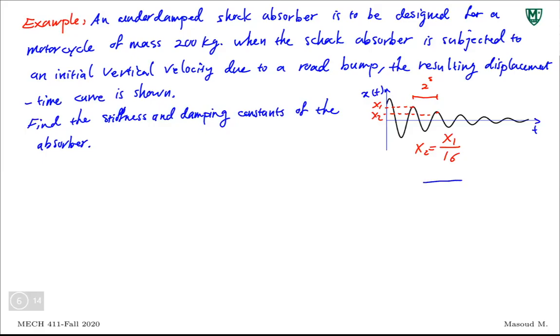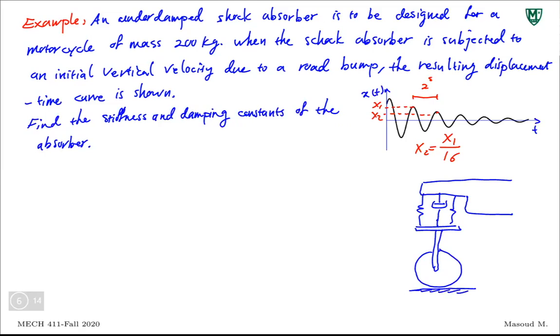And the shock absorber, I'm going to do my best to remake it at least to some degree. It's a pretty ugly shock absorber. But by that, they're trying to say we have a damping there, we have springs here, and then from there, it's connected to some mass. But you get the idea, I guess. To make it a little more obvious, that's a motorcycle, I can do this. And these are K over 2, so the whole thing is just K, and this is the damper. Some bump on the road, and as a result, we get this measurement.